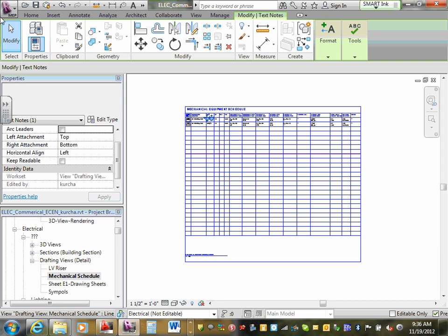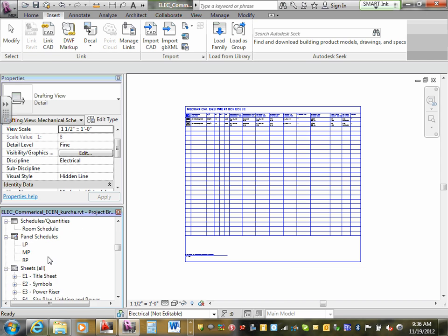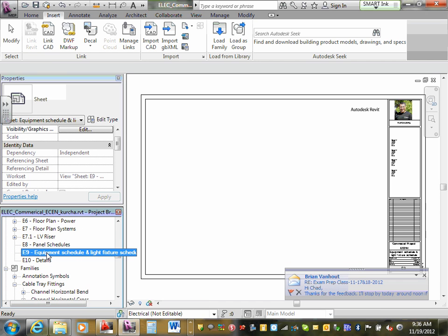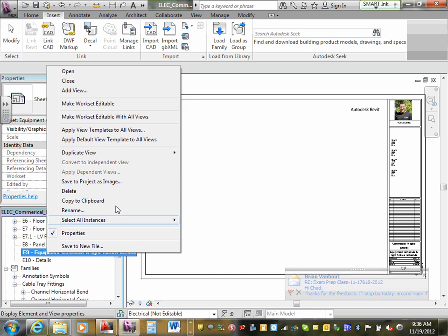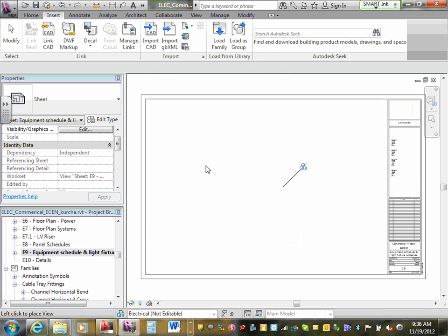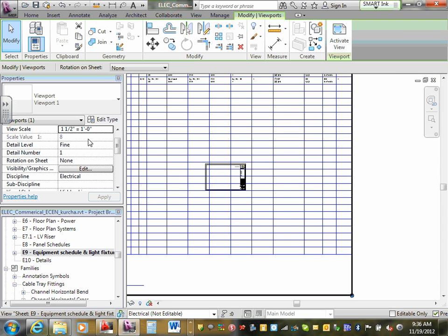Last thing, let's go drop that schedule into my sheet. Now I'm going to go back into sheet E. Which E are we looking at, gentlemen? E9. Go to E9, please. Click on E9. Add to view. Here's my mechanical schedule. Add my mechanical schedule to view. Drop it. Look how big and nice and ugly it is. So you need to adjust it, obviously.